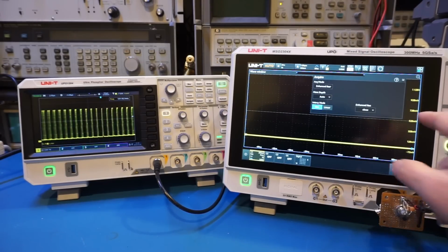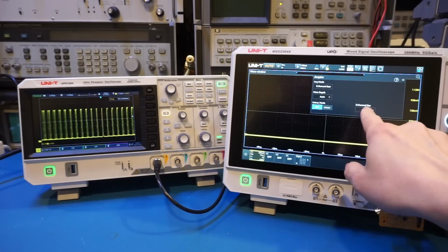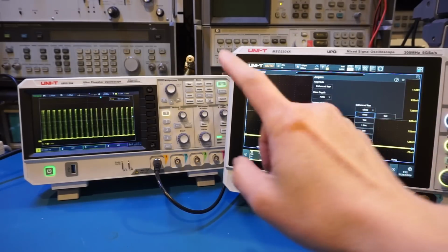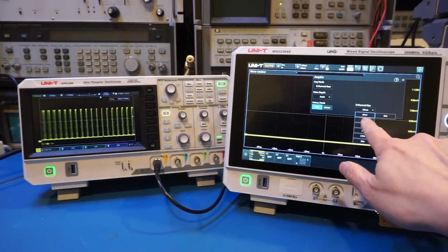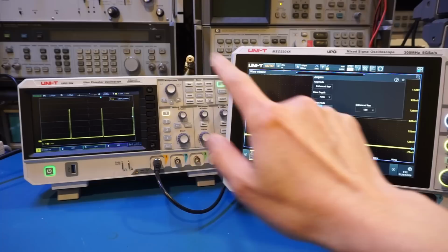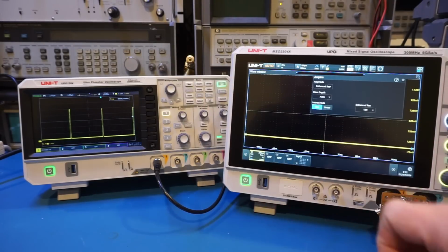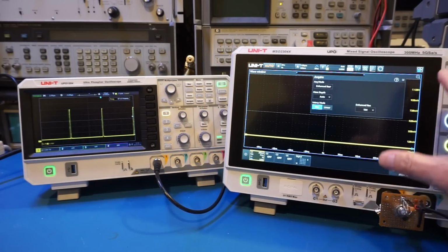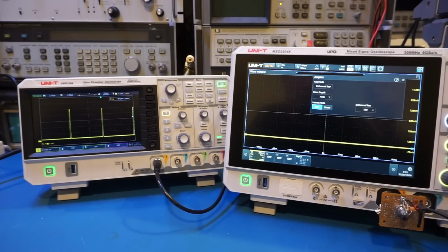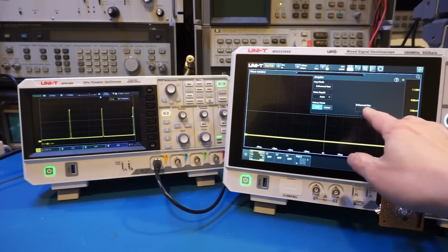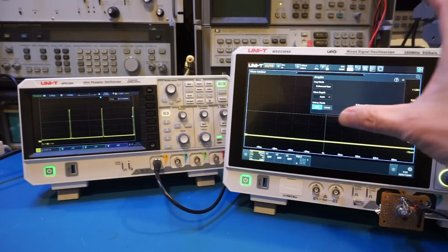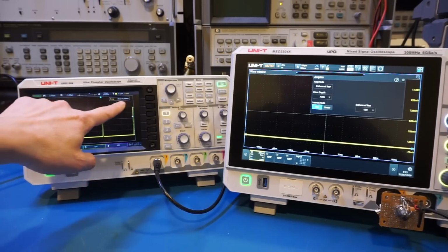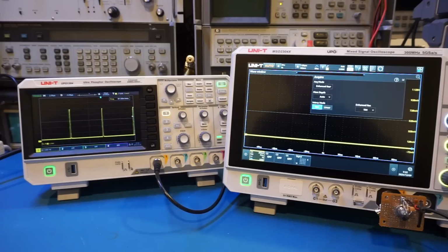You can see that right now because we don't have any additional bits, it didn't impact the triggering rate. So let's actually add 1 bit. And you can see immediately the triggering rate dropped to 88 kHz. Although bandwidth is not impacted, the waveform update rate is significantly slower. So as I suspected earlier, even though adding 1 bit to the resolution did not impact the bandwidth, you can see here from the triggering rate, the refresh rate definitely dropped.